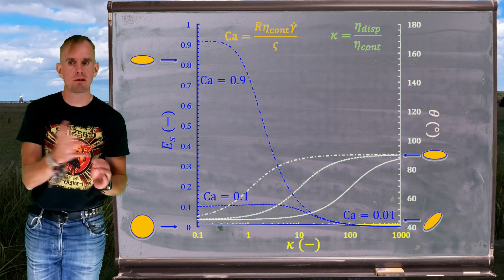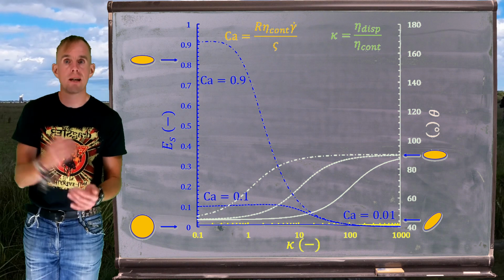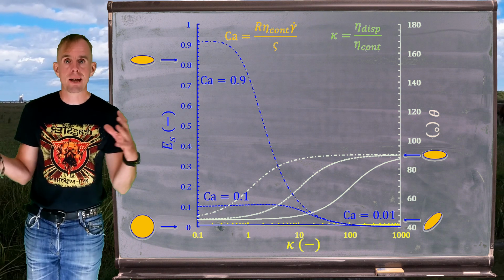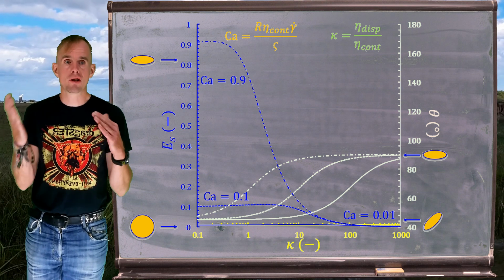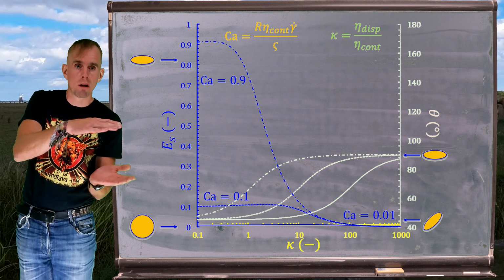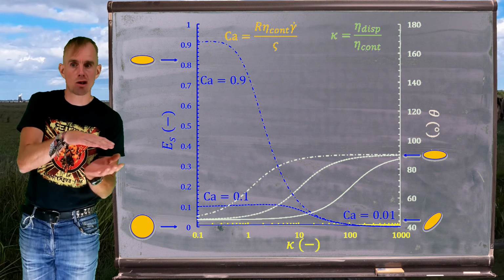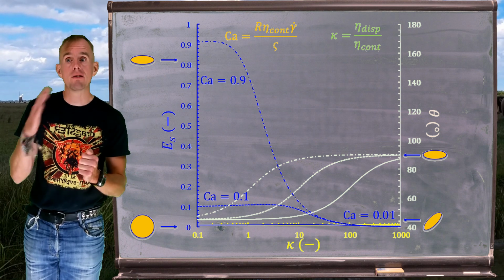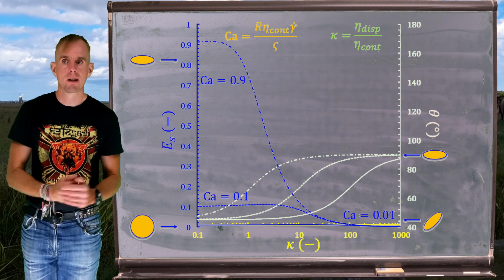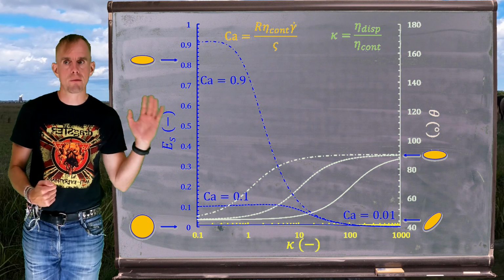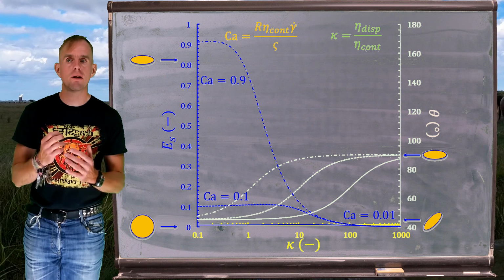As we increase that viscosity ratio, again what we see are the ellipsoids tending back to spherical droplets, and their orientation going more and more aligned with the flow direction, or 90 degrees to the axis that is perpendicular to the flow direction. So there is a visual summary of droplet behaviour in shear flows.